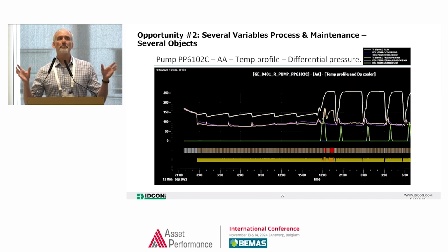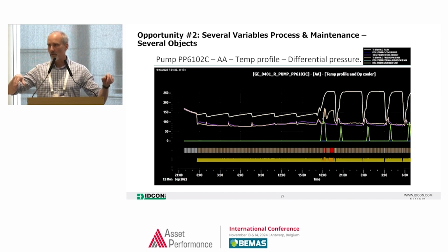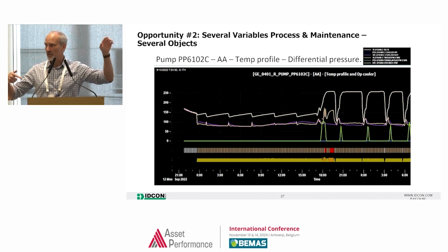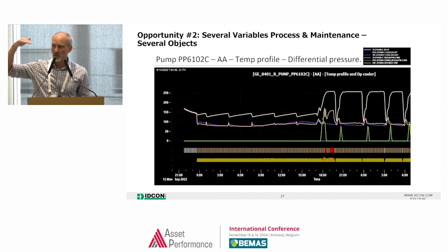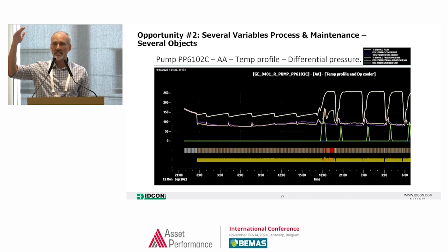So if you think of a pump, there's 2 bearings in the pump, 2 in the motor. We can do the temperature and vibration on those. But what if we start adding data like seal water pressure, seal water flow? I start looking at, of course, discharge pressure from the pump, inlet pressure from the pump. Maybe I even take the position of the valve. Now I teach the computer, and they're going to learn very quickly. When you close that outlet valve at 68%, maybe I get cavitation in the pump, right?